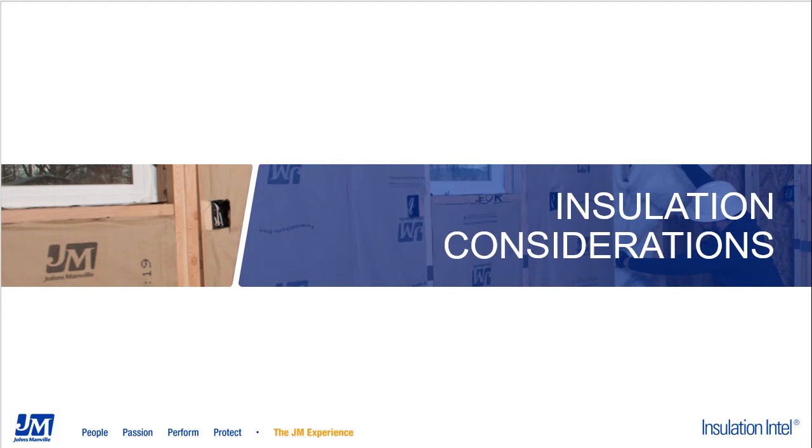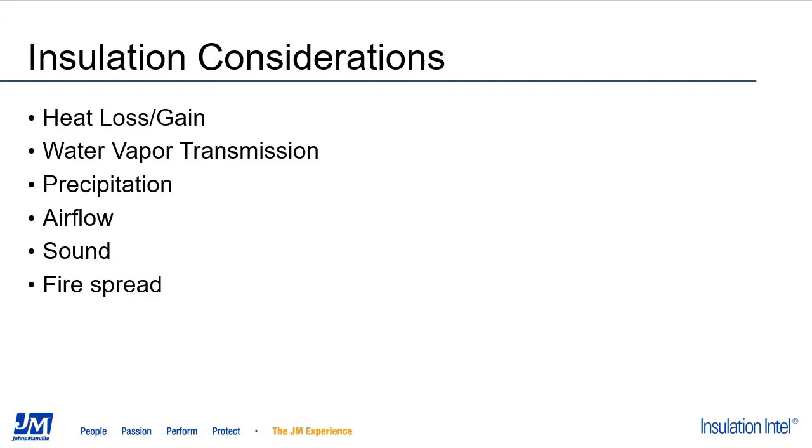Well, let's get into insulation considerations here. When looking for the right insulation for your product, the primary consideration is often the ability to control heat loss or gain. Insulation's primary role is to help control temperature inside a building. However, depending on the building or region the building is in, you may be interested in other properties like controlling vapor transmission, precipitation, or airflow.